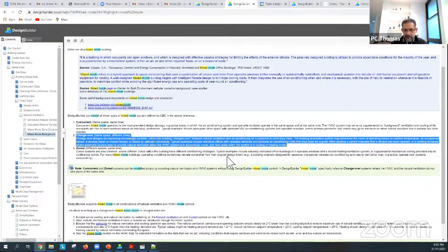When you're doing air conditioning, it's simple. You know how much air is coming in. There's a fan. The fan brings the air in. You can calculate that. When you do mixed mode, you suddenly have to do heat transfer calculations and mass transfer calculations, because the airflow brings mass and the mass brings humidity and heat. And its control strategies are dependent on two or three things happening together. So it's complicated. In real life, it's easy. You feel hot, you open the window. If it's cooler outside, it works. But mathematics is a different thing.